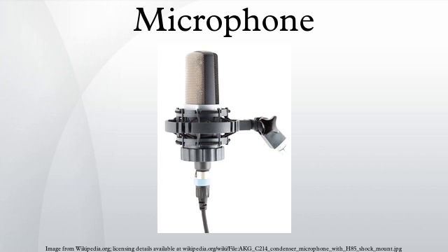Most professional microphones are low impedance, about 200 Ω or lower. Professional vacuum tube sound equipment incorporates a transformer that steps up the impedance of the microphone circuit to the high impedance and voltage needed to drive the input tube. The impedance conversion inherently creates voltage gain as well. External matching transformers are also available that can be used in line between a low-impedance microphone and a high-impedance input.